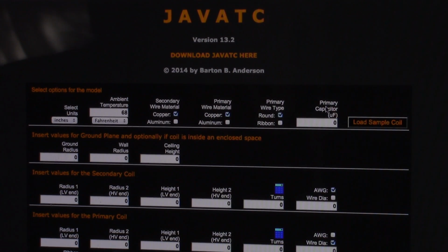I know that when I tapped, my primary tap point for this coil is around 4 turns. If I don't get an answer that tells me 4 turns and somewhere between 30 and 70 kilohertz, then I'll know that I took the measurements wrong. So I'm going to try to reverse engineer what I did for that coil. So let's enter some of this data.